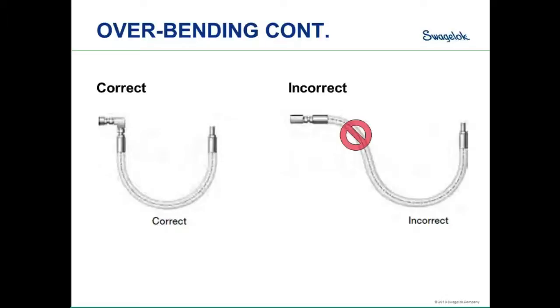The illustration above represents the most common misinstallation, as there's too much stress being created near the end connection. This stress then could jeopardize the integrity of the hose immediately or over a period of time. An easy solution would be to add an adapter fitting to alleviate this stress, as you can see on the left-hand side.